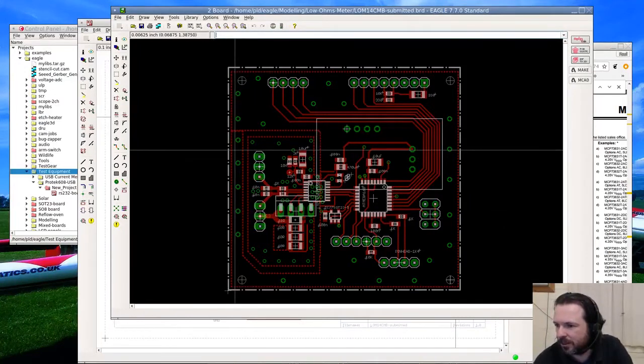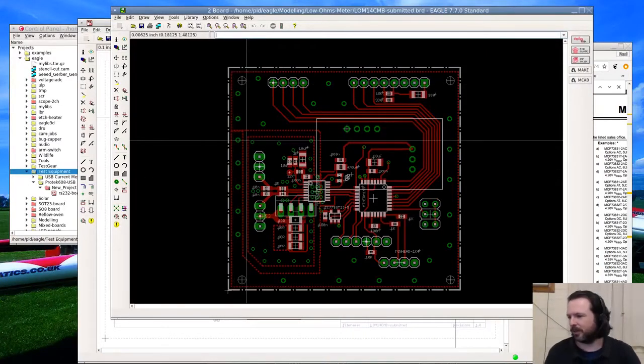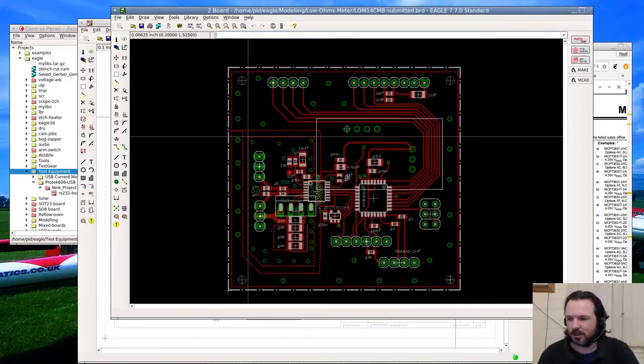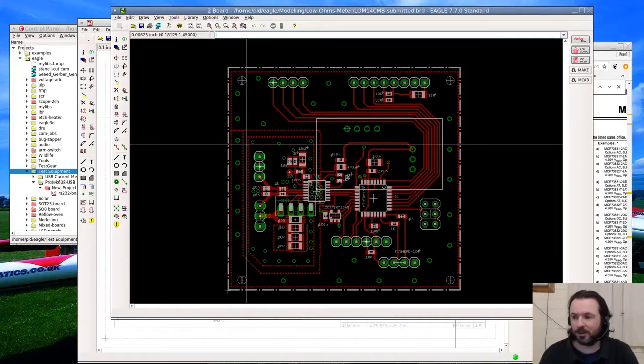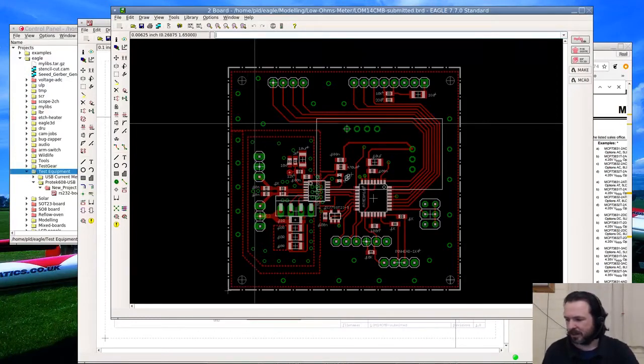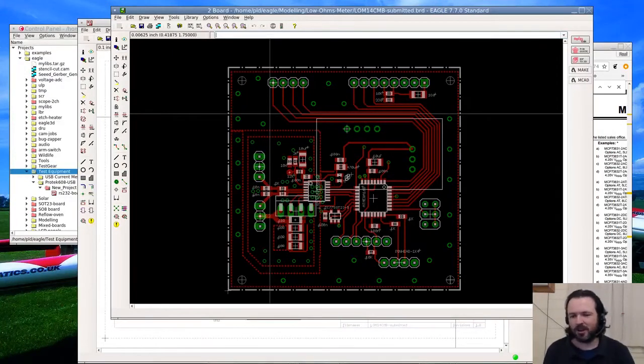Let's see, I take it you can adjust turn off with different resistor values for R1. Yeah, you can. It's where half the fun is. When you change the PNP transistor, or just buy a new batch, you have to go along and start trimming the values again and pick something that suits what you're after. It's annoying, which is why I tend to buy a reel of 1,000 or something like that, so I don't have to do it too often.